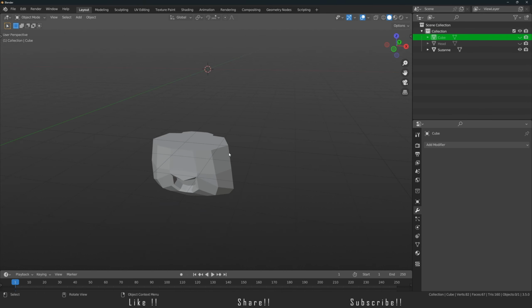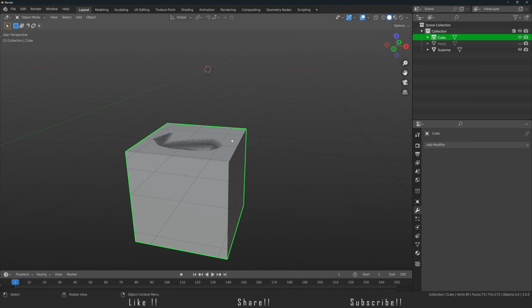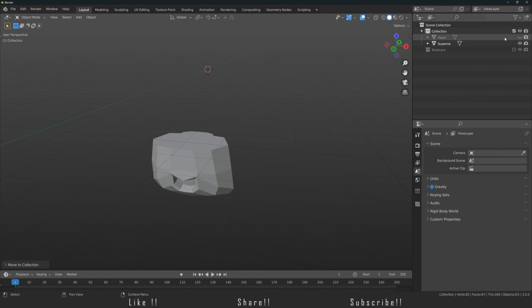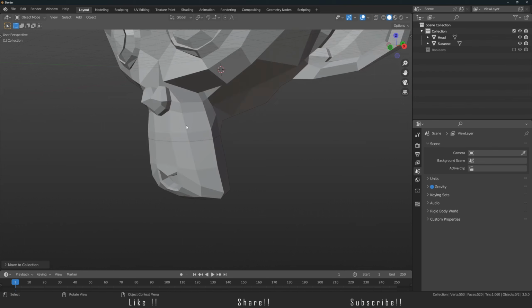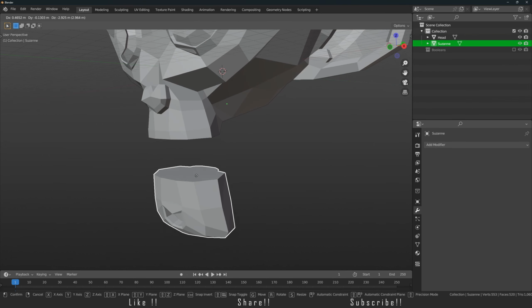At this point, if you want to, you can delete the cube, but I don't recommend deleting all your boolean objects. Instead, create a new collection called booleans, and put the cubes and the keys over there. I'm going to show you the reason why. So let me just disable it and unhide everything. Now we have the two of these things, right?